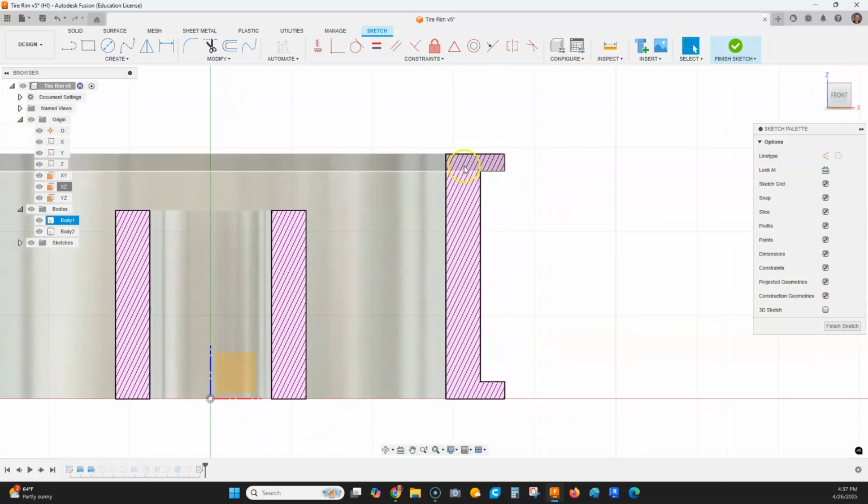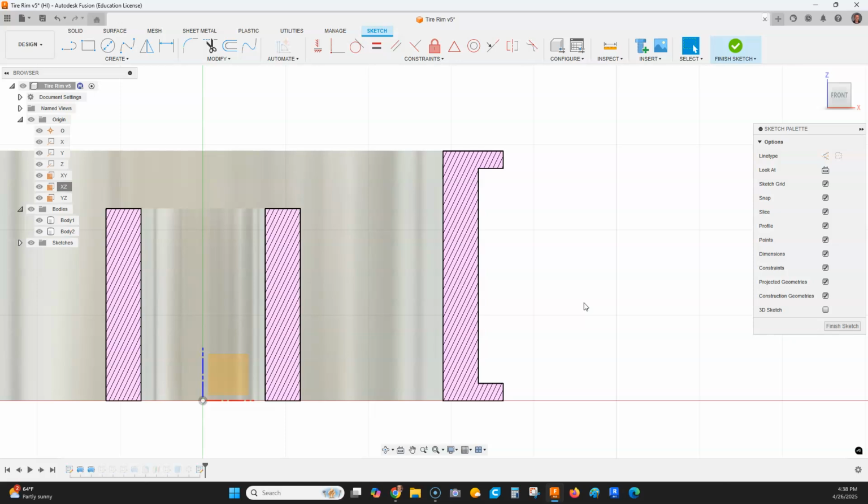What you see where there's lines cut through are section lines. That means material was cut. So in essence, we took kind of a knife and cut right down through the center of our original design, and we just got rid of the other part momentarily. Now we want to see where the material is. Notice that there are no diagonal lines or no purple or pink colors. You don't see any of that in this area here, and that's because there was nothing cut. There's only air in that area. You would only see the section lines where we had material cut.